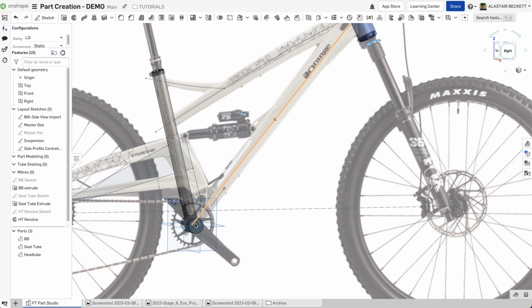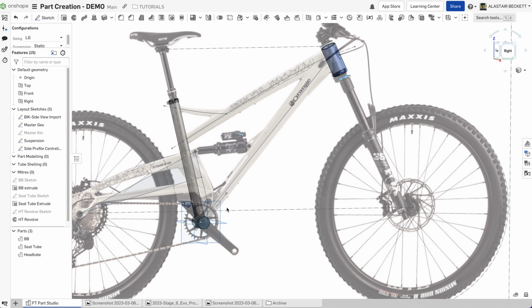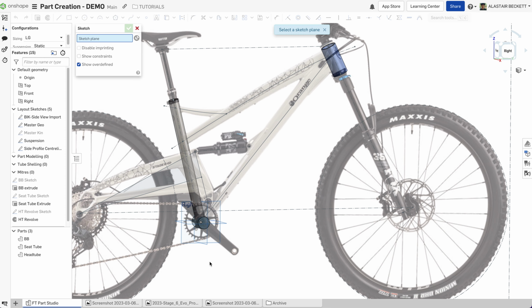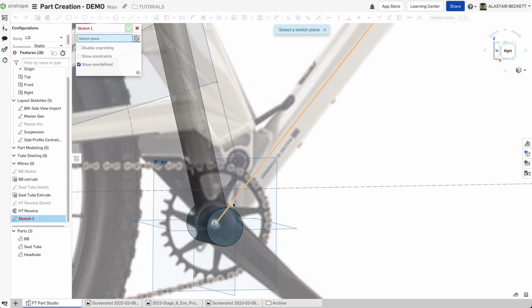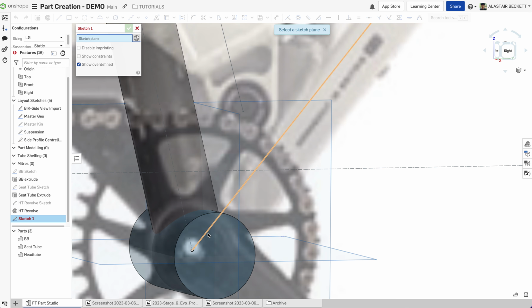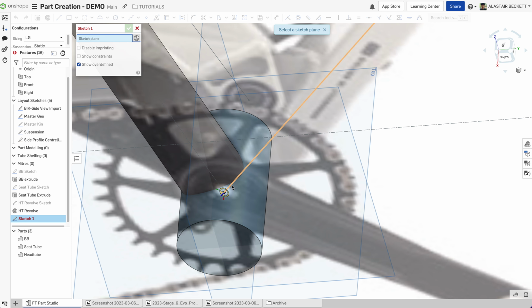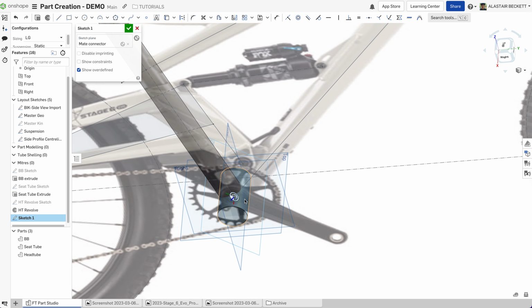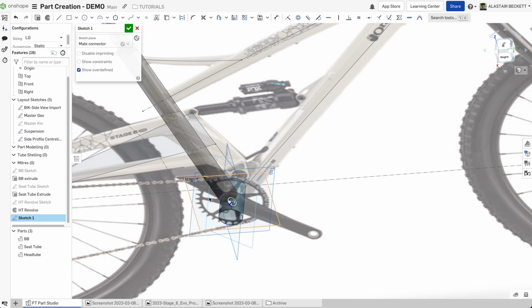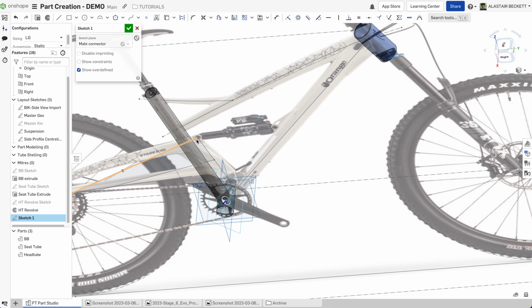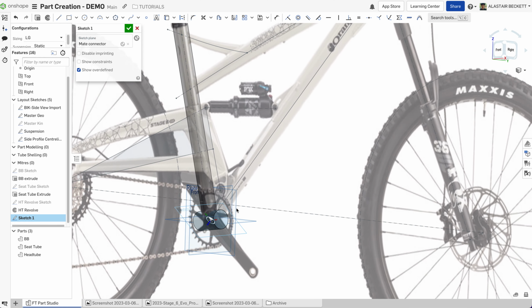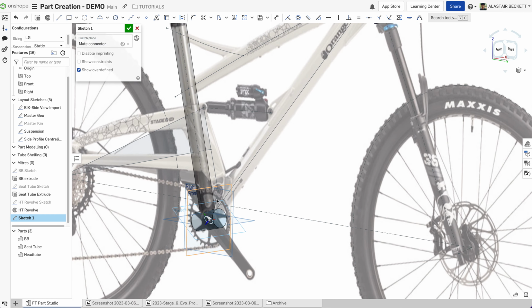So what we're going to do is start with the loft feature. Basically it joins two different sketches, or multiple different sketches, together. So we're going to have a sketch at the start and a sketch at the end of the tube. So let's start with that. Again, click on Make Connector, select the tube or the sketch of the down tube. This is where it gets a little bit complicated. That's the one we want as you develop multiple parts in one part studio, because the other parts that you've already drawn or modeled actually start to cause you some grief and get in the way.